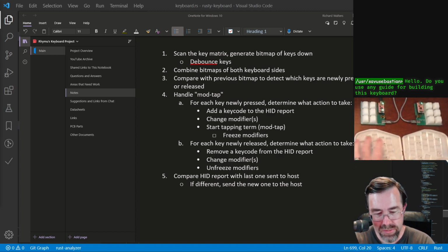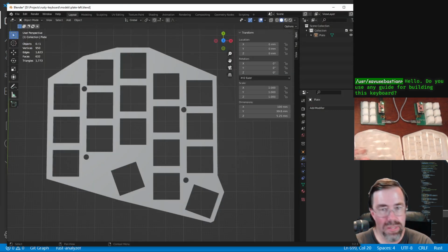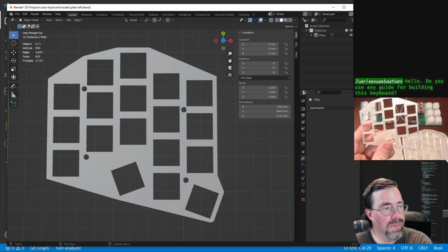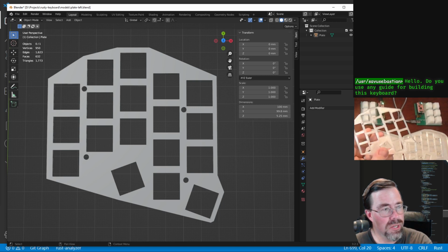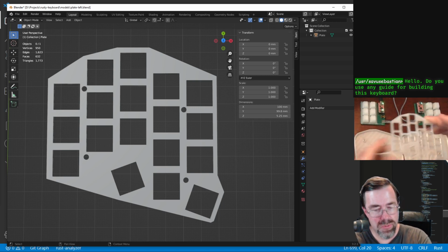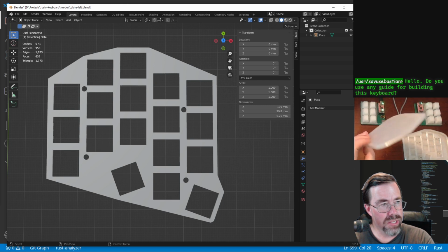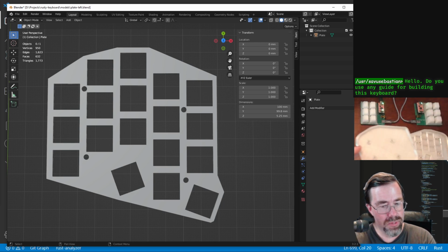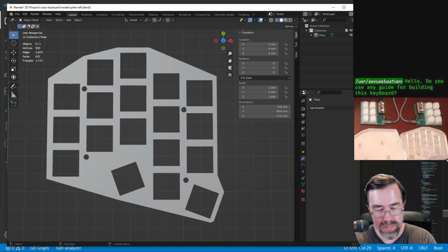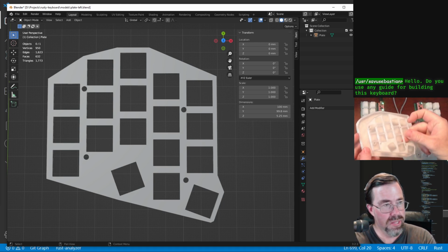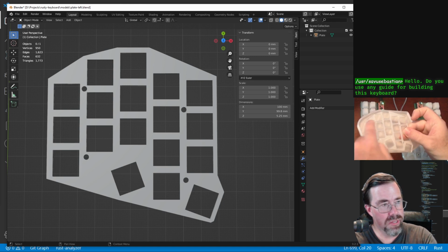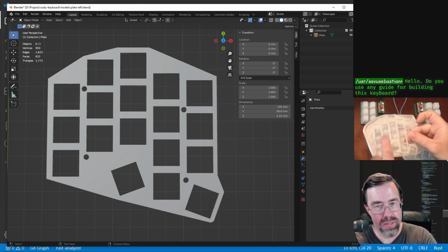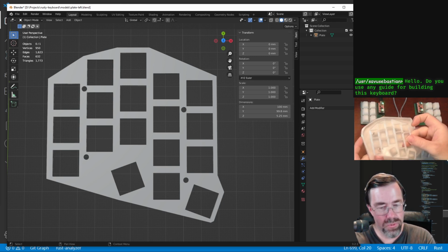Oh, that's another thing I forgot to mention. I designed this over the weekend. The plate that's going to hold the switches. So this is the bottommost chassis piece, 3D printed, right? And it's got these nickel inserts for screws. The PCB goes on top. The PCB goes on top of that, and then on top of the PCB goes the switch plate. And then the switches fit in all of these holes, right? And then these 4 screw holes are what hold everything together.